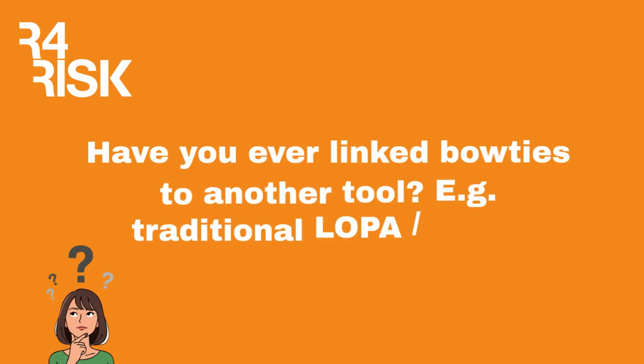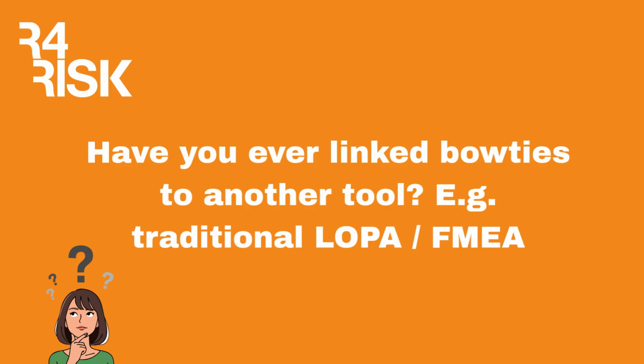Our regulator has complained that some bow ties are not granular enough, e.g. look at Buncefield, with very high consequence. Have you ever linked bow ties to another tool, e.g. traditional LOPA or FMEA, to provide more detailed justification, with the bow tie providing a higher level summary?